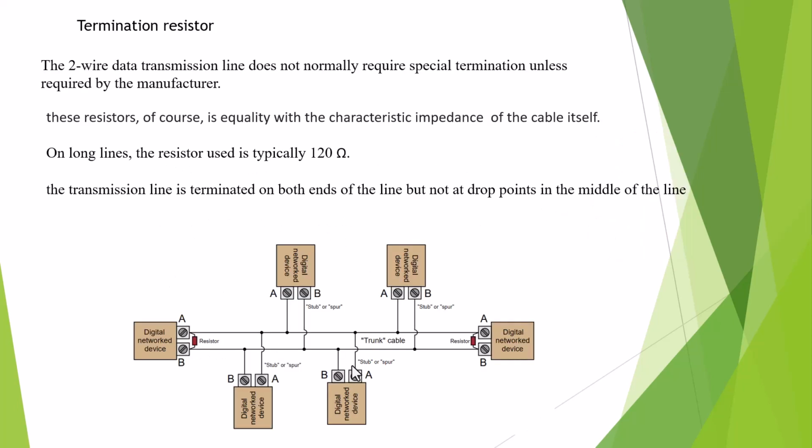Okay, termination resistor. Actually, if you have a two-device RS485 connection, you don't need a resistor. But if your line has multiple drop devices, you need a termination resistor.